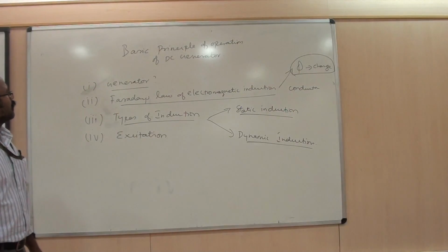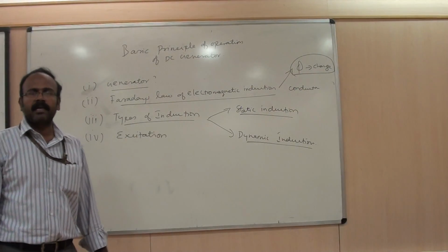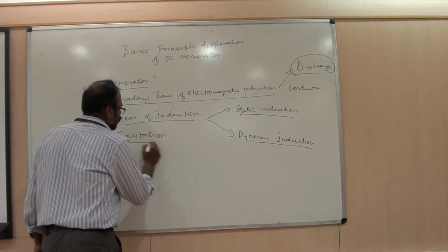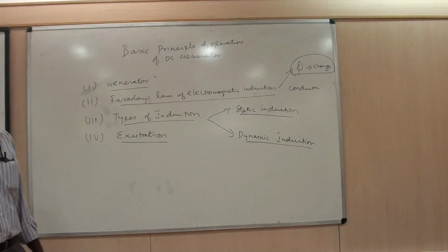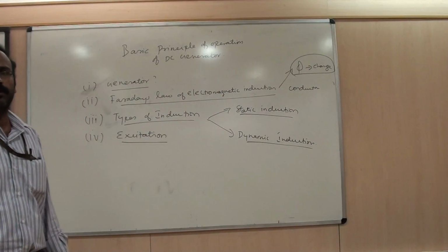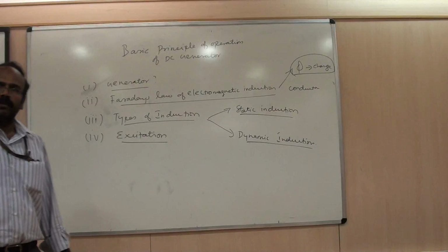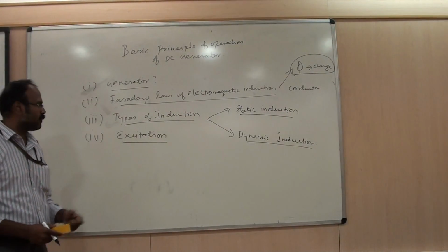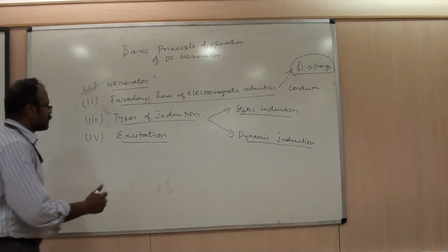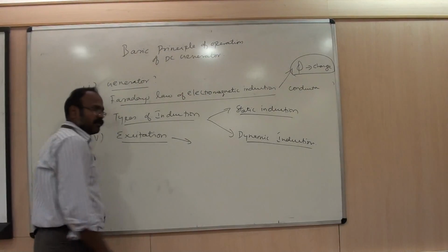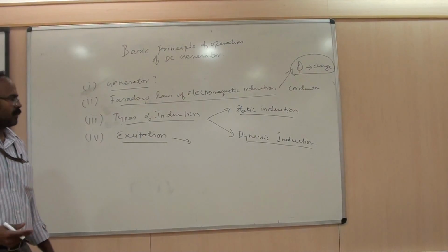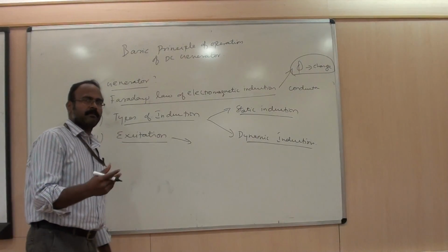In most of the rotating machines, the electromechanical energy conversion machines, we usually use electromagnets for the production of flux. We won't use any permanent magnets. We go for an electromagnet, particularly when the size of the machine is too large. So excitation is nothing but the phenomenon of production of the flux by applying an electrical supply to the coil.